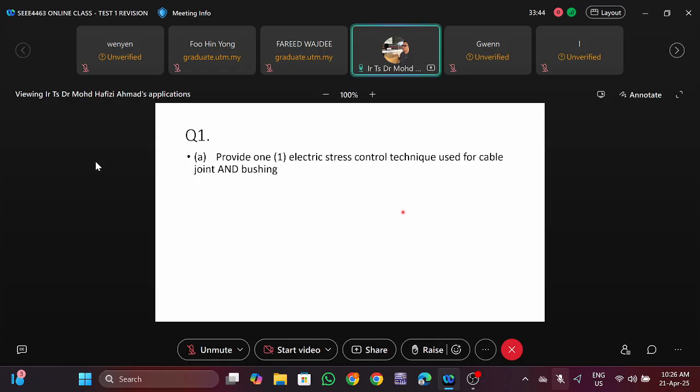If the electric field is over the dielectric strength of that kind of material, it can give energy to electrons to travel, and then it can cause ionization. For the case of solid insulation, it can cause thermal runaway, and finally a breakdown of the solid insulation. That is something we don't want.